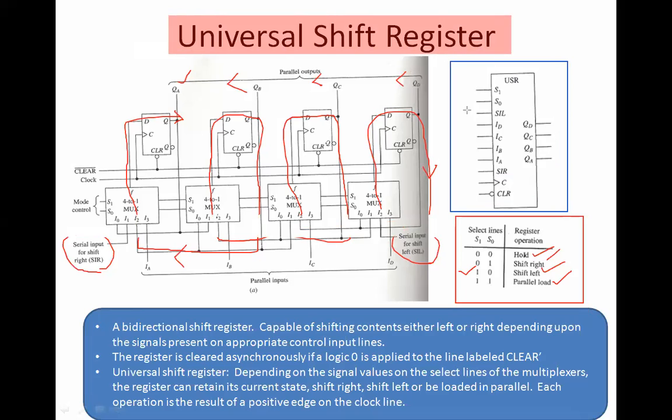So you have clear and you have clock signals that are actually enabling each flip-flop. So you can see that the clock signal is connected from this line, and it keeps going to each flip-flop here. To each flip-flop it is connected in this fashion, right? And then if I want to clear my data, whatever data that is inside the flip-flop, that can be done with the help of clear option. So all the data can be cleared, which means I can feed 0 to them.